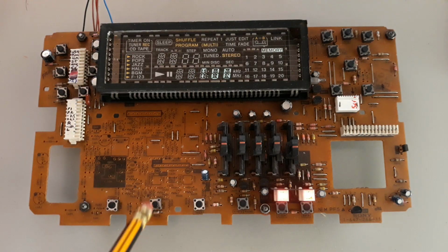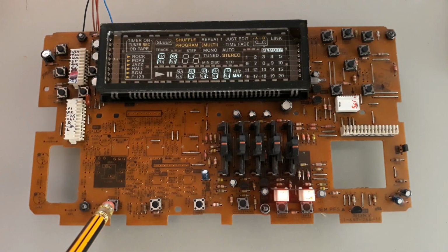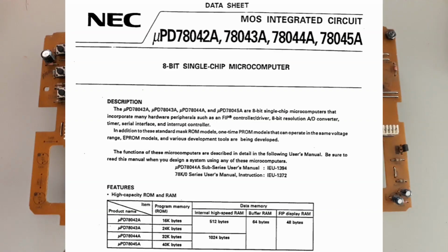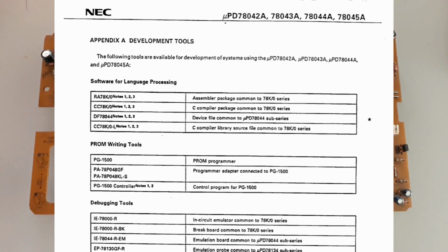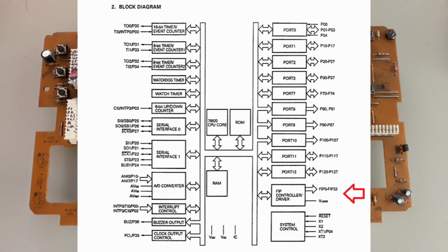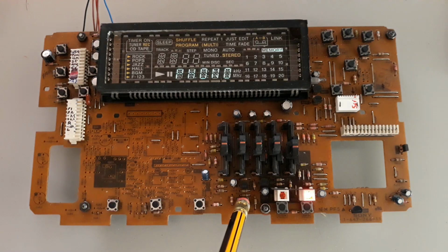All of the display animations and keyboard interactions are controlled by a device from NEC reference uPD78042GF. This component belongs to a family of devices that combine an 8-bit microprocessor with an integrated VFD driver. This combination made them very popular in consumer electronics of the period.